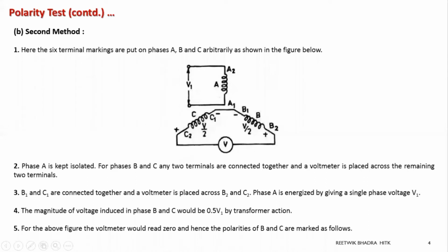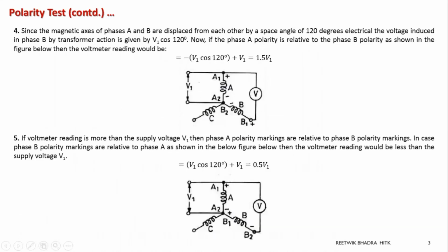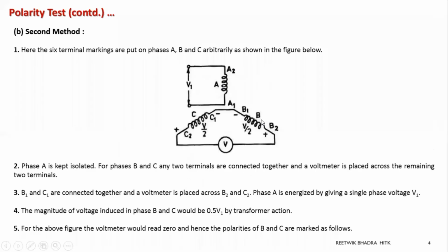Presently I'm thinking about this only because there is isolation between the phases over here. If there is a problem in supply, this A phase may get damaged, but B and C phase will not be affected so much. Over here, the whole circuit is being used from A to B. We are using this whole circuit. If there is a problem over here and we want to measure a current over here also, it will short circuit this whole phase. Along with A, it will short circuit B.